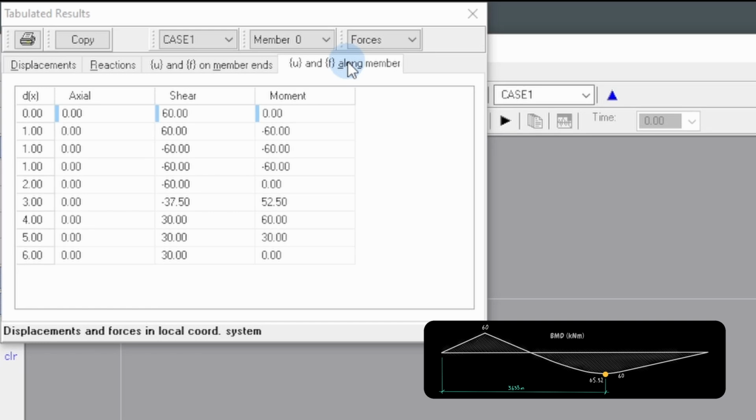This is not a problem, it simply means that LinPro and Dr. Jim are using different sign conventions for internal moments. Such apparent contradictions are very common in structural analysis because sign conventions are conventions. There's nothing absolute about them. Indeed, later in this course, Dr. Jim will dispense completely with putting signs on bending moment diagrams. This is because drawing bending moments on the tension side of the members is the sign convention. It's simple, elegant, and totally unambiguous.